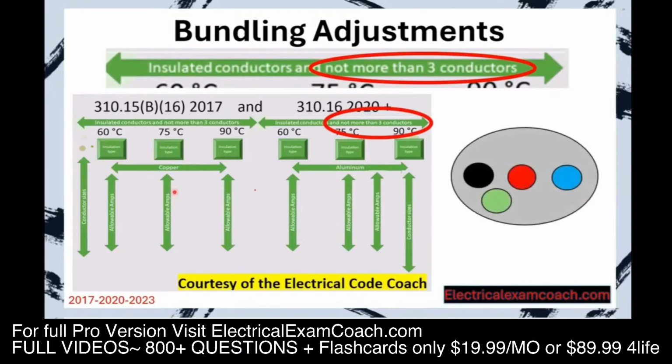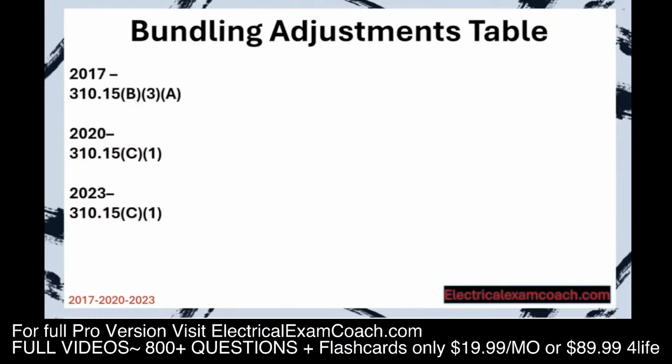Let's take a look at it. Let's imagine that we have a piece of conduit here and we pulled in a black, red, blue, and an equipment grounding conductor. What this table is saying is that those ampacity values listed down below in this table are true as long as you have not more than 3 current carrying conductors in a cable, pipe, or raceway. If you do have more than that, then we have to do what's called a bundling adjustment. Let's learn about our bundling adjustment table. Head to this respective table depending on your code cycle.